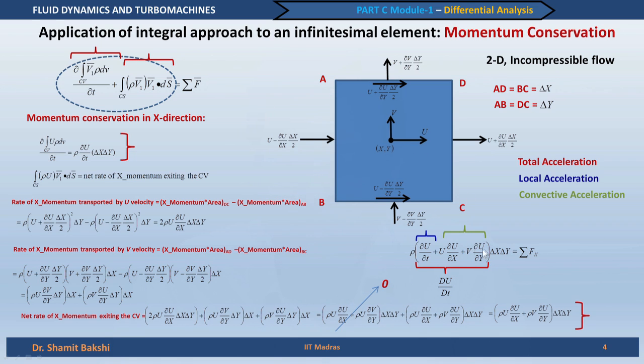Now, this part of velocity is very important to consider in the description of a flow using a Eulerian field. This was demonstrated in our first chapter, when we considered a flow field which is independent of time, but when we considered the velocity of a fluid particle, it was changing with time. So, the fluid particle definitely experiences an acceleration, but the velocity field in terms of our Eulerian description is independent of time.